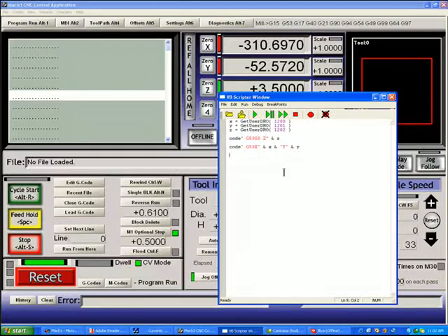Let's say at that point, we've moved our tool back to a machine coordinate where we wish to change our tools. We could do other jobs, such as zero those controls. So we can type set DRO 0, 0. This is a Mach 3 command which will set the X DRO to whatever number you put in, and it does that by changing the fixture offset coordinates, or it's the same as pushing a 0 button.